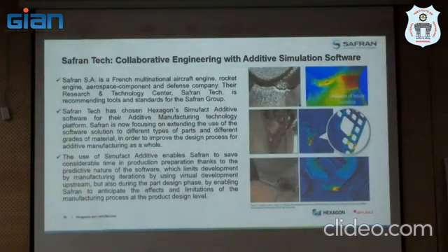These are the other examples of how we can optimize and further validate. So we always say that the lattice looks good, any unit cell looks good, but when it comes to fatigue, those are the weak points. So we always have to be careful. It looks fancy, but the more connecting points, the more weak points.